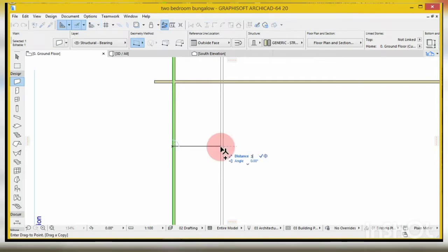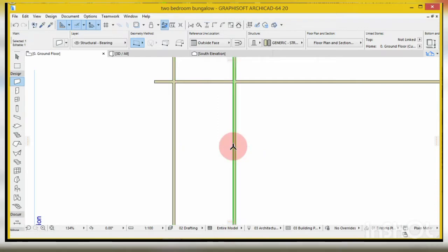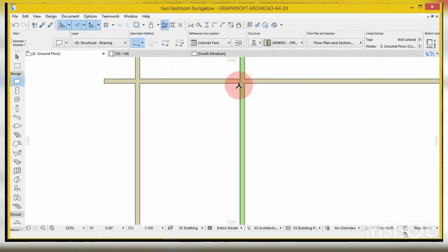So it's normal wall. So let's say it's 3,600. But I have to include the thickness of the wall too, because I need 3,600. So typing this 2,000 to reduce it. For example, let's just see what I'm talking about. So you can see it has reduced it. But I want 3,600 as the dimension of this wall. So I'm going to come here and measure.